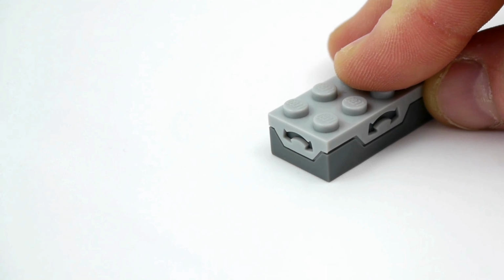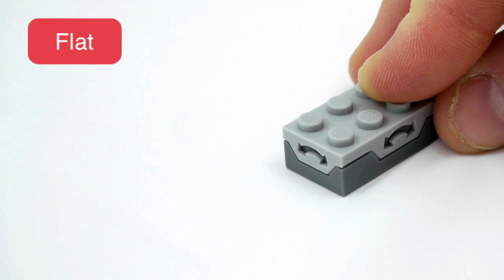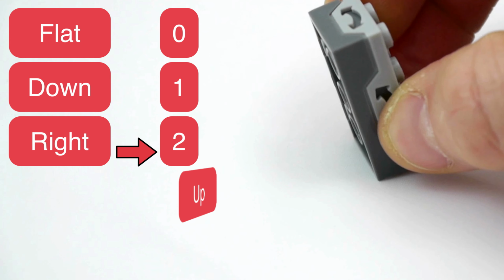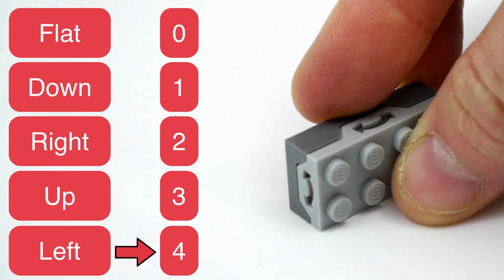Now let's take a look at the tilt switch sensor. This provides one of 5 values, depending upon the direction the sensor is pointing in. When it's flat, the value is 0. Tilt it down, it generates 1. Tilt it right, it generates a 2. Tilt it up, it generates 3. And tilt it left, and it generates a 4.